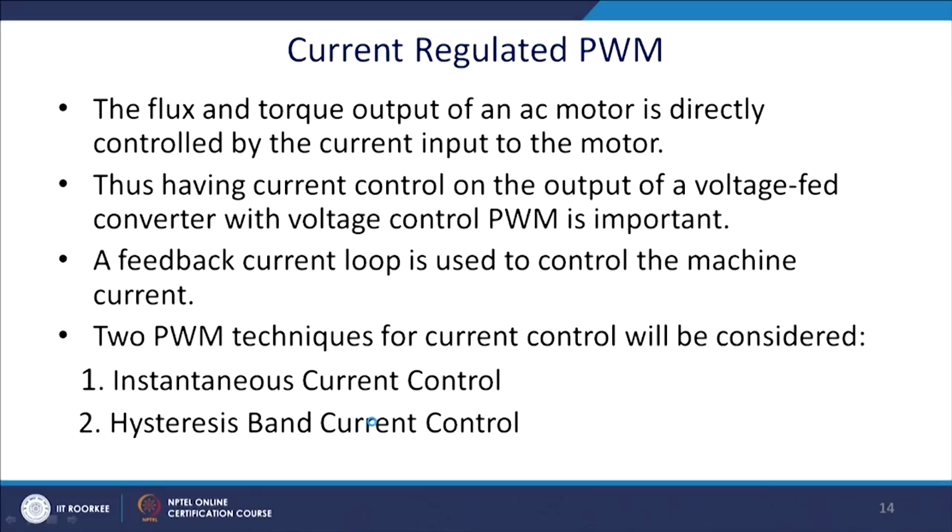Now, current regulated PWM. This is very important for our drives and FACTS points of view. Since the flux and the torque output of the AC motor is directly controlled by the current, and the same principle is used for the STATCOM for the DQ based technique. So, current based PWM control has been put to use for FACTS devices.